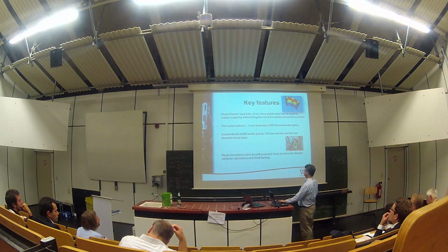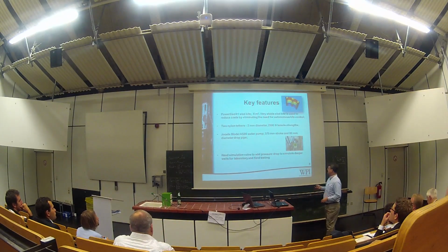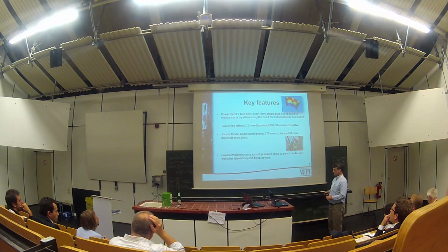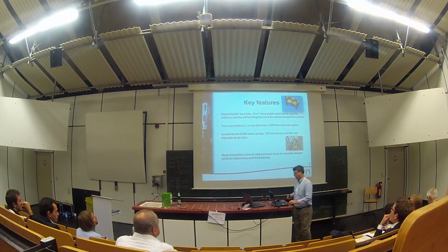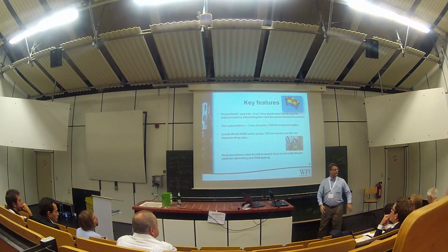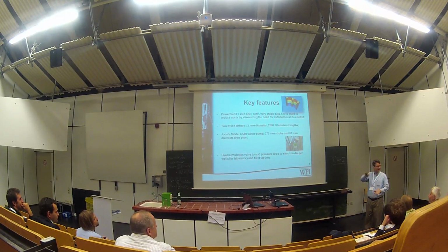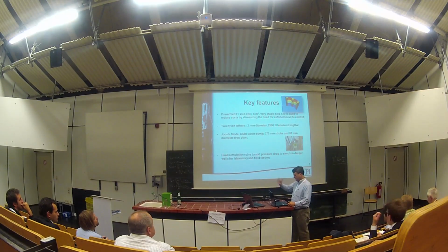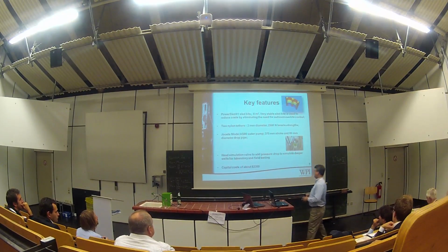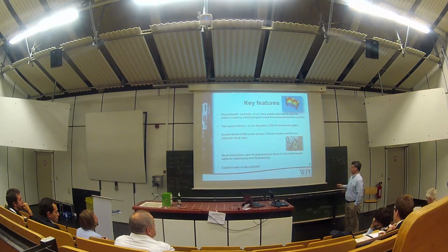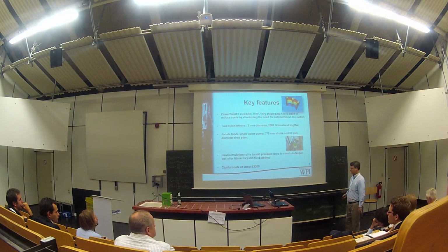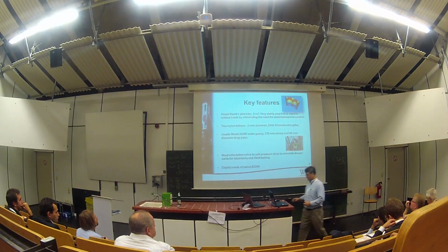And again, you see some of the details there. We do have a head simulation valve here. This is meant to simulate deeper wells for laboratory and field testing. You see we're on a beach here, actually, in New Hampshire, USA, and people don't like you digging a 50-foot well, right? So we dig like a 4-foot well, put a bucket down there, and simulate higher pressure drops, deeper wells, with essentially an adjustable orifice. And we did meet our design goal. What you saw was built at material and fabrication costs of about $2,300.